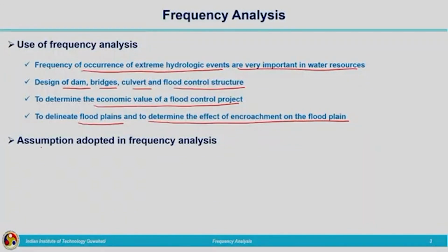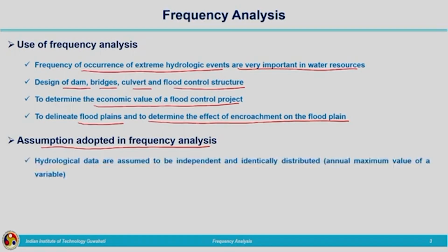Now, coming to the assumptions adopted in frequency analysis, there are certain assumptions we make before carrying it out. The first assumption is that hydrological data are assumed to be independent and identically distributed, that is, the annual maximum value of a variable. For example, annual rainfall data are considered independent.